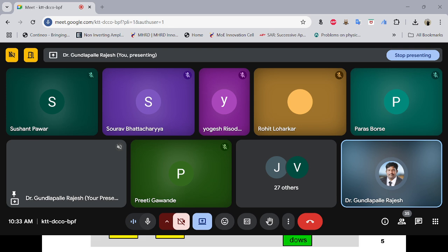Whereas with CAN you can see a simple architecture. See here, the number of lines is more, which makes it clumsy. With the invention of CAN, there is only one high-speed CAN bus, connected as a central bus with your dashboard, and to this CAN bus the anti-lock braking system, engine control, transmission control, active suspension, lighting, power seats, air conditioning, all the electrical as well as mechanical features are interfaced or interconnected.